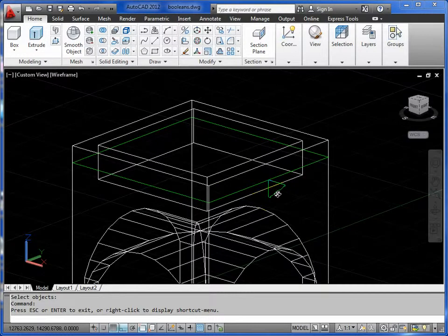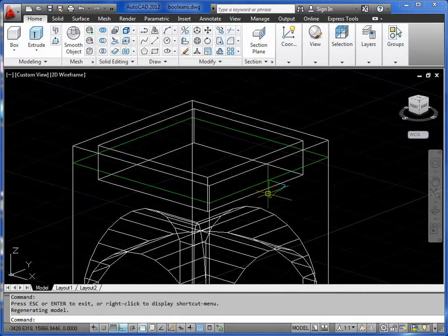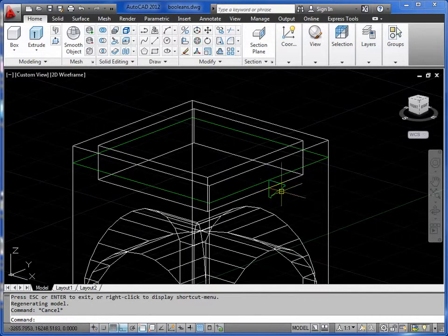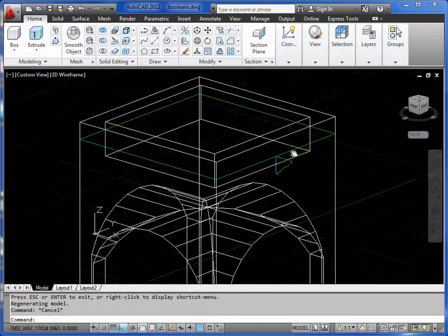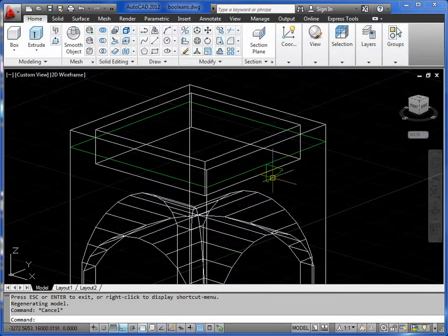Okay, what we've got here is this pale blue shape is a profile of a cornice, and I want this to go around the building. So I'm going to use the extrude command, but slightly cleverer. So we'll extrude along a path so that it follows the green line. If we just use the normal extrude command, it would just go in this direction, either forwards or backwards in that direction. The objects always extrude in the plane that they are normal to.